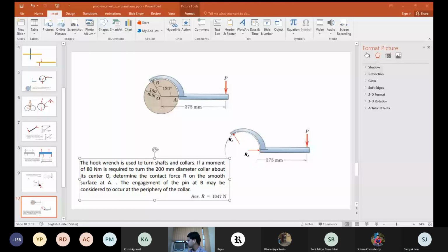Okay, please try to solve this. Sir, but weight will also pass through the center of the circle. Which one? Weight. Nothing is said about the circular object. I think either the center of gravity of the circular object is not the center, or it is constrained by something else which is outside this question. One of the two things has to happen, otherwise the circular object will not be in equilibrium.